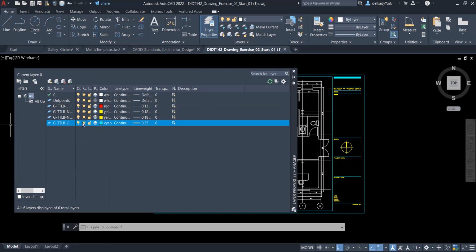This is more convenient when the drawing is going to be more than 100 layers, not dealing with 5 or 6 or even 20. So this becomes more convenient because the drawing is going to get very heavy, and you don't want any of the layers to be in the cached memory of CAD. Here, even if we turn it on or off, the layer is still in the CAD cache memory. So that's the difference between those two.